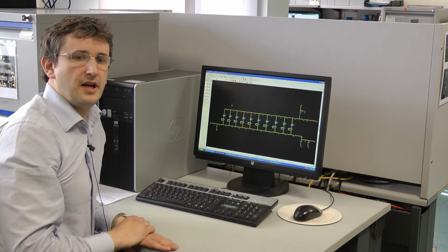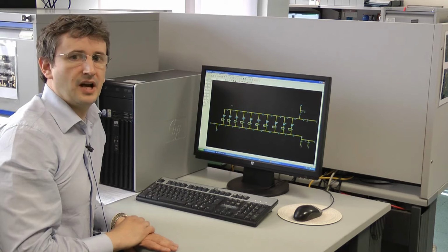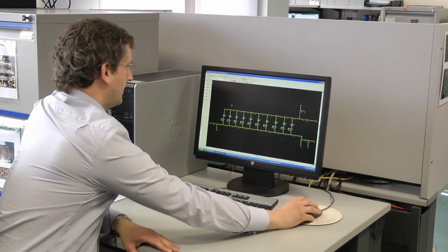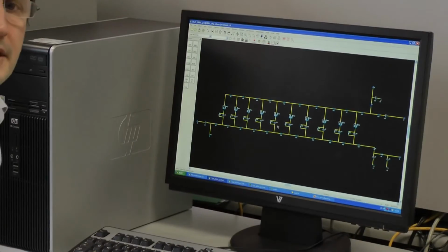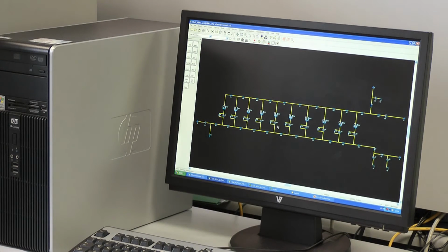If we wish to increase the power without compromising the upper operating frequency, we have an option, and that is to introduce MIM capacitors in series with each device gate.